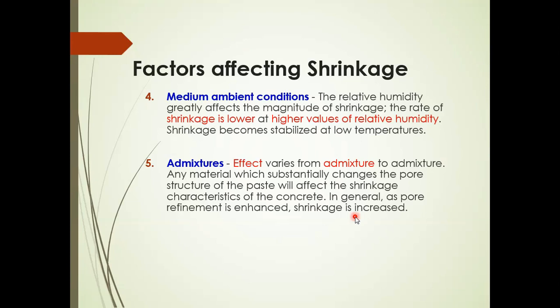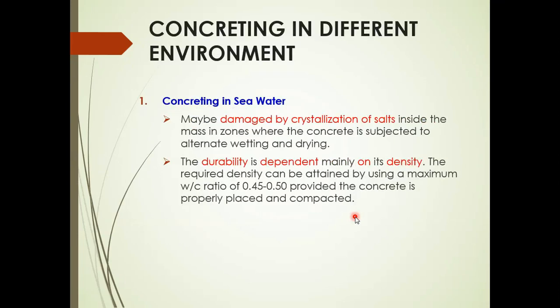And also the admixture that we add, the effect varies from admixture to admixture. So any material which substantially changes the pore structure of the paste will affect the shrinkage characteristic of the concrete. As the pore refinement is enhanced, the shrinkage increases.